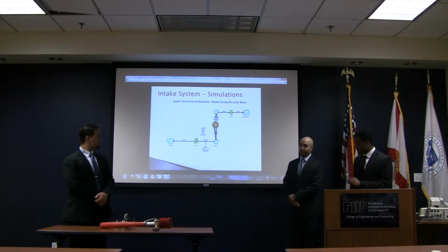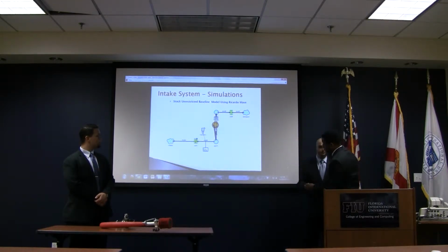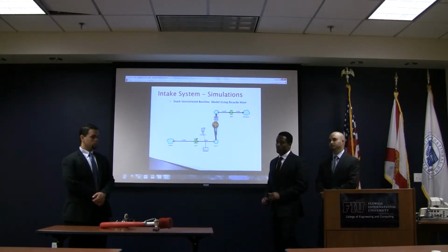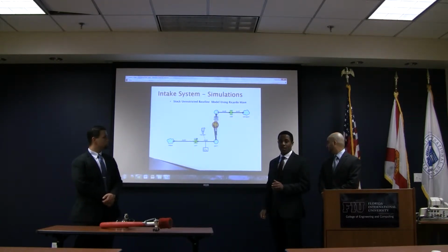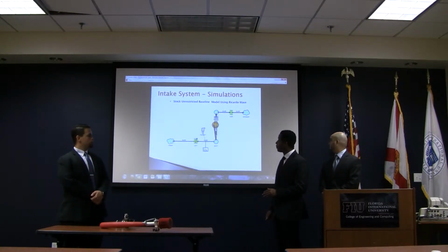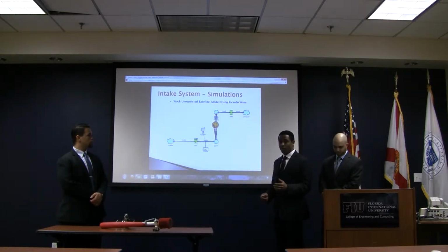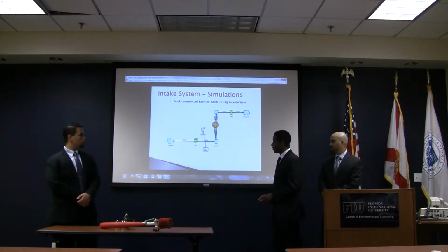And now my partner Mike Menos is going to discuss our computer simulation activity. To get a better idea of how our changes affected the engine, we utilized Ricardo Wave, a 1D engine and gas dynamics simulation tool that allows us to see how the intakes affect the entire system. What Ricardo Wave does is essentially treat the entire engine as a series of ducts and orifices, giving the orifices, like the throttle orifice that you see here, a K value in the modified Bernoulli equation.